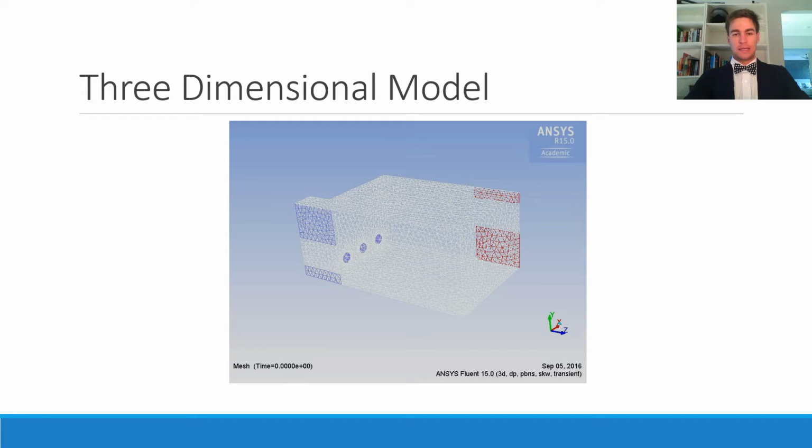The image shown is of the three-dimensional model with a completed mesh. The inlets into the zone are coloured blue and the outlets are coloured red. There are two types of inlets for the anoxic zone 1: the inlet and the A-recycle pump, of which there are 3. The flow from the inlet is from the return activated sludge pump, otherwise known as MRAS, and the daily inflow into the plant. The flow rate gives a velocity of 0.149 meters per second.